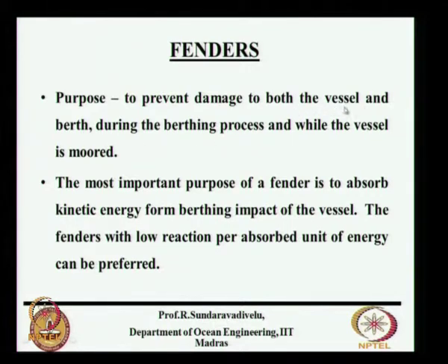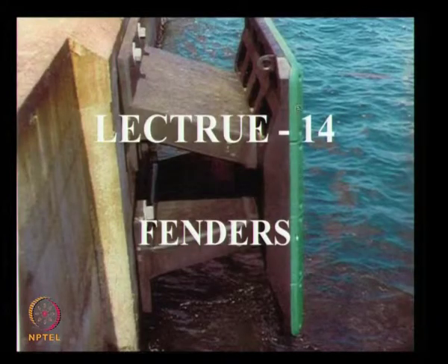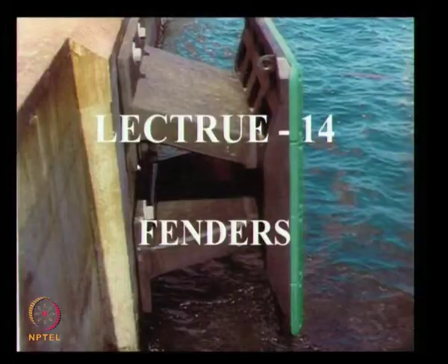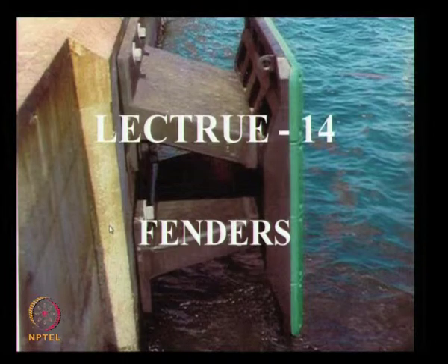To prevent the damage to the vessel, normally the vessels are designed for the pressure of about 40 tons per meter square. The bigger vessels are designed for 20 tons per meter square. That means whatever the pressure that is coming from the board to the vessel should not exceed 20 tons per meter square for a bigger vessel and 40 tons per meter square for a smaller vessel. For the berth, we have to design for the berthing force, that is the force which will be transmitted through this. So, this berthing force we have to calculate and design the berth for that.